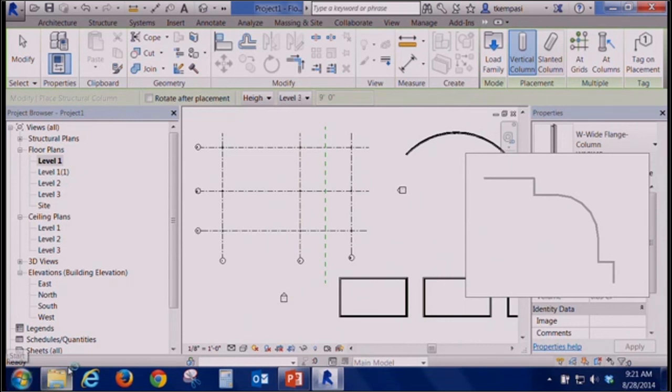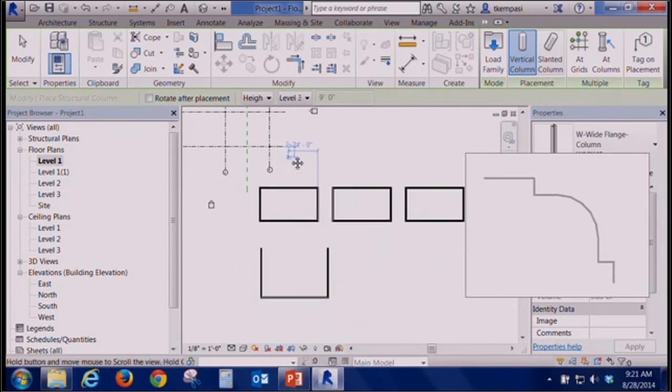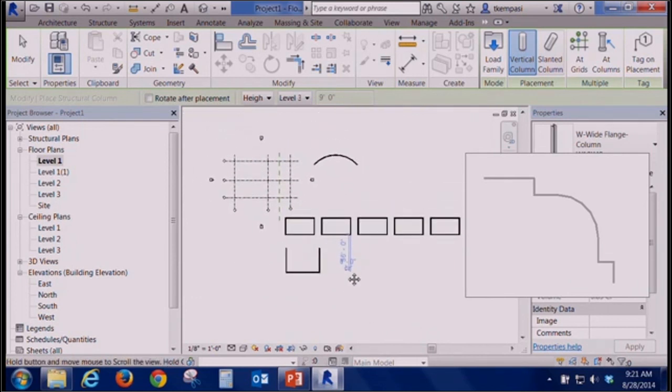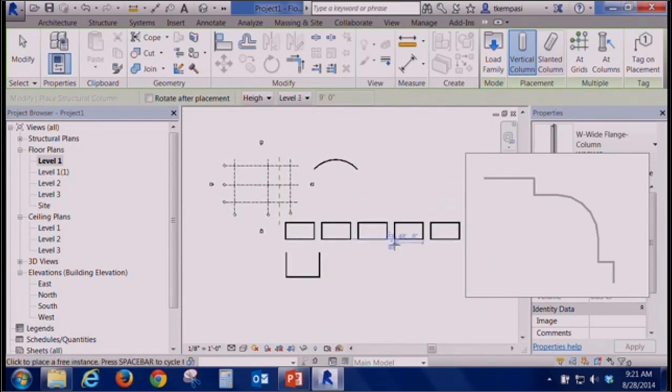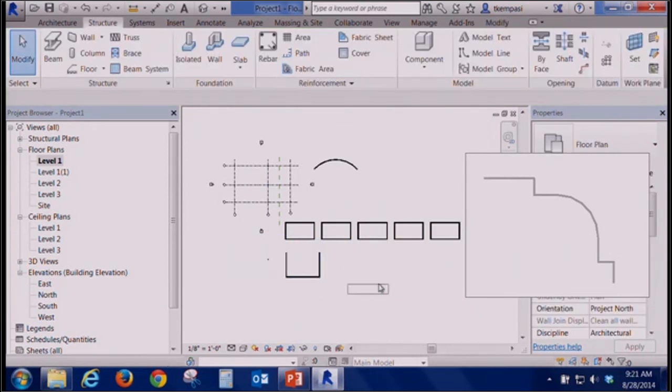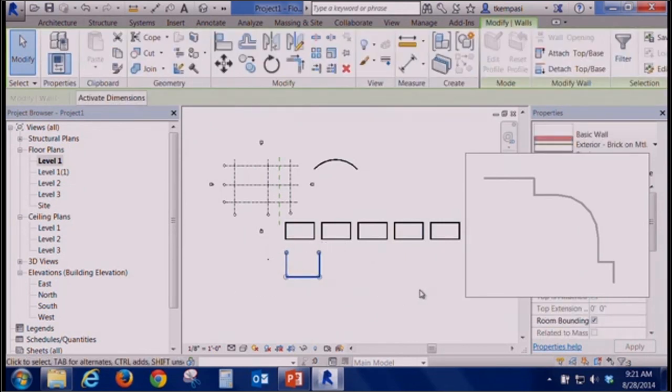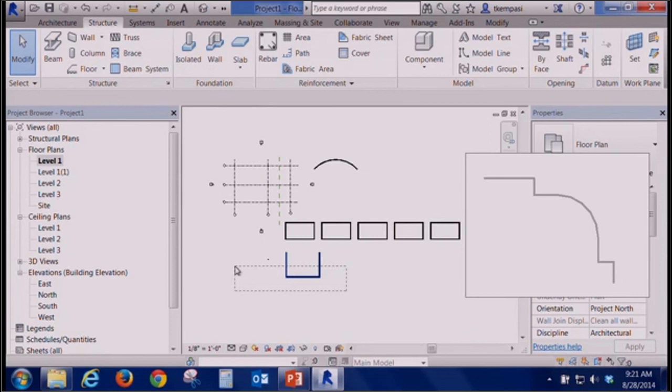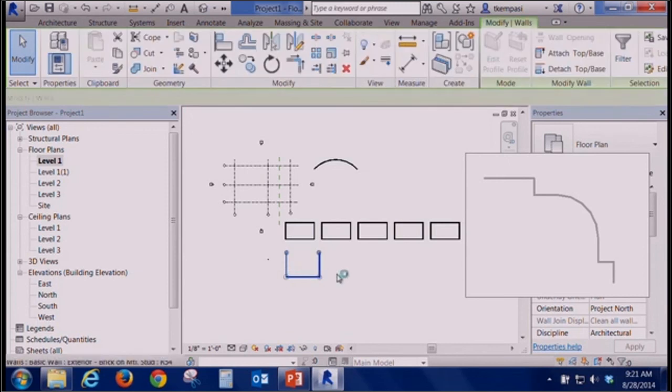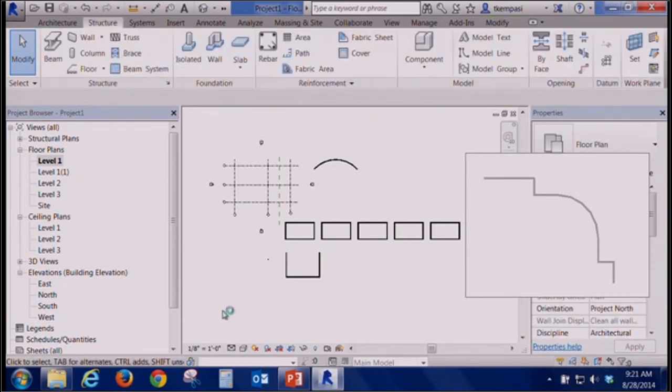Couple of things on just overall interface and selecting objects and everything. So if I click and hold and mouse to the left, it's gonna select anything that I have crossed. Okay, so you can see I mouse to the left here. I'm just crossing those two vertical walls, but it's still going to select those. Okay, if I mouse to the right, it's going to select anything that is included in that window.